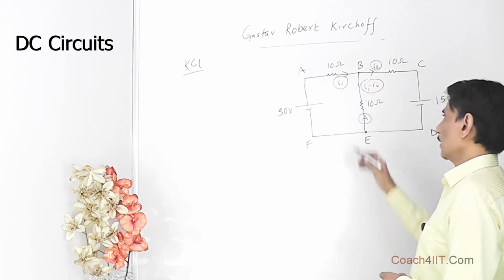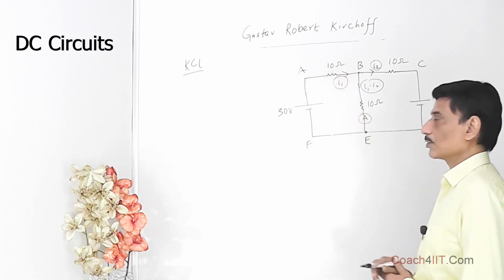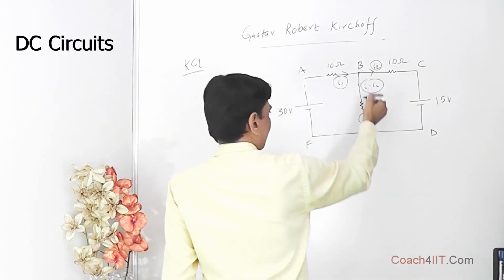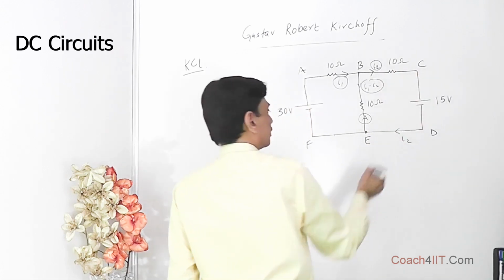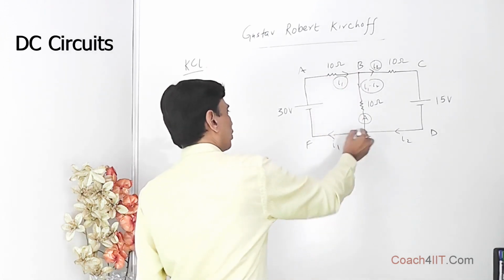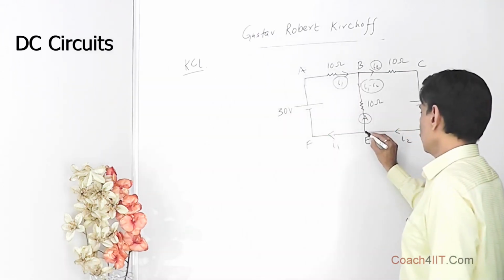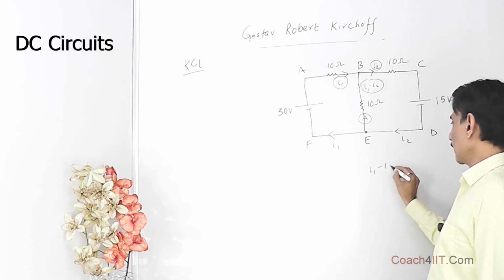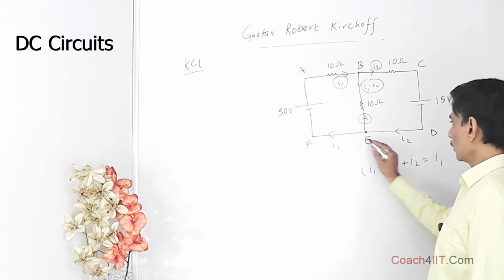When we are so engrossed, at times we make the mistake of taking currents as resistances, and resistances as currents. So these encircled ones remind us that these are the currents. So I1 minus I2 comes over here, I2 is here, so over here this is I2 only. In this whole arm the current will be I2 only. If I1 we have taken over here, then I1 only shall be flowing in from E, F, A, B. When we look over here also, I1 minus I2 is coming from here, I2 is coming from here. So this makes I1 only.